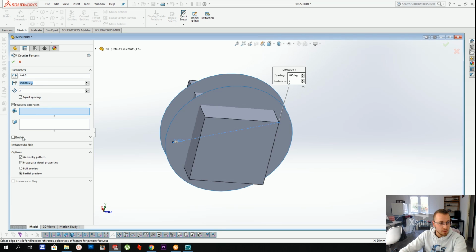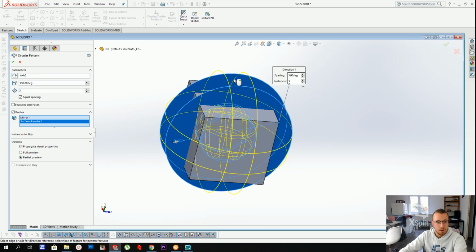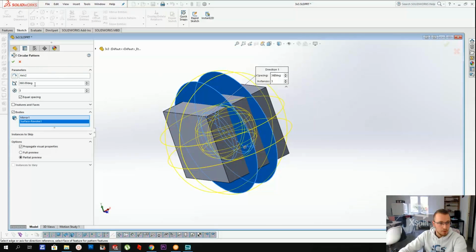If you put in 360, it's just going to divide 360 by the number of surfaces, but technically you could put 240 and it's going to be the same result, because it's going to do 1 every 240 divided by, well, the number of angles that you're going to have. So here you're making 2 copies extra than the first one, so it's 2 copies in total, so 240 divided by 2, 120 degrees. If you do 360, it's just going to divide the whole total by the number of copies, so it's going to work as well.